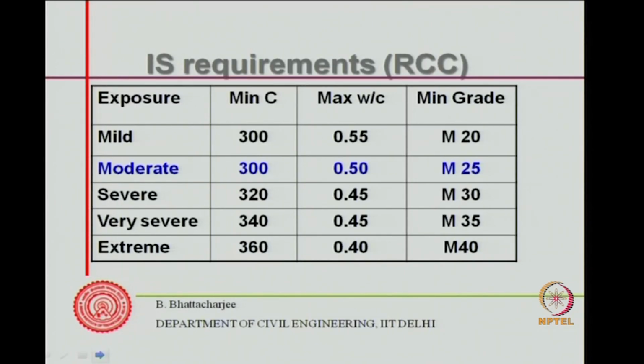Then it says that you use the water content from past experience if it is available, or from Table 5 of IS 456-2000, from the durability requirement. This is the table which gives the durability requirement. If you see the prescriptions, they are given for various exposure conditions: mild, moderate, severe, very severe and extreme.